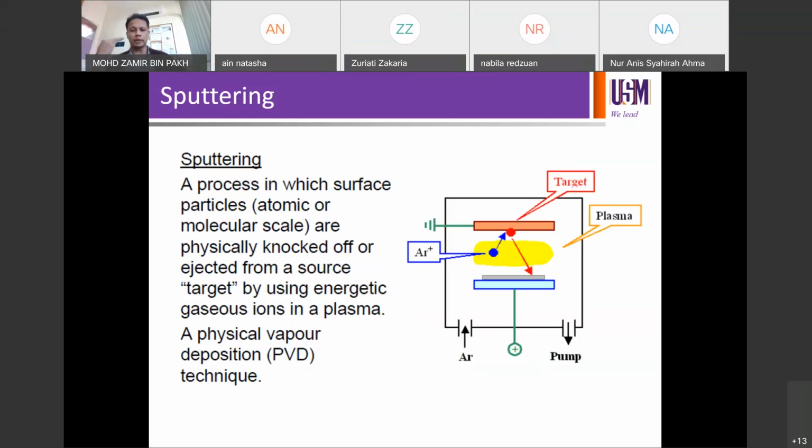So we normally have our mechanical shutter on top of the target to block the sputtering. The sputtering runs, but it's not everywhere yet. Or you can in fact do a cleaning of the target before the actual deposition, so you can actually sputter the material, but you block the deposition from reaching your substrate by having a mechanical shutter. That means the target is actually sputtered, but there is no deposition on the substrate.